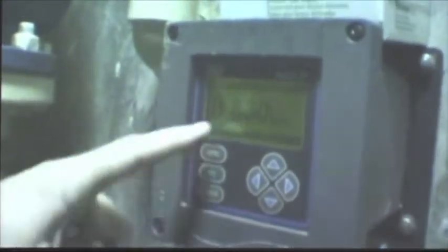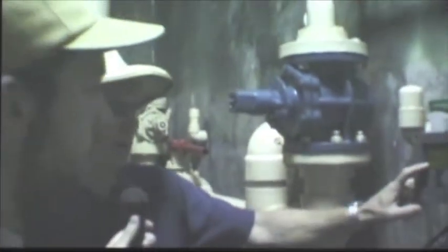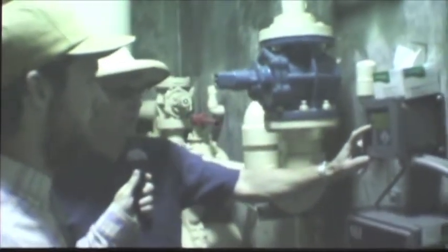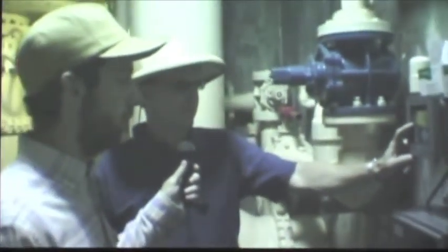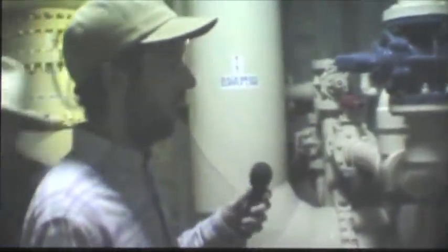Right here, this is the meter that measures the influent turbidity coming into the filters, and right now it's at 0.83. Our limit going out of the plant is 2.0, and so that just shows you the high quality water that's coming to the filters, and that'll show you right afterwards how much turbidity the filters are able to remove. But that's an excellent number. So the lower the better? Oh yeah.